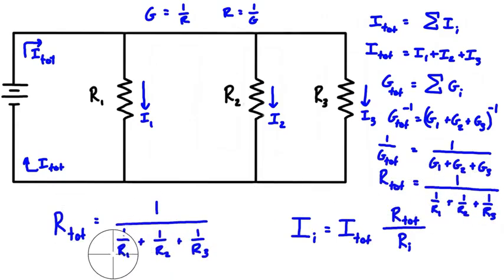So that's exactly how you derive this equation, which gives us the equivalent resistance of the circuit from the perspective of the battery. So instead of having these 3 resistors, we could cut these and remove the right-hand side of the circuit and then just connect one equivalent resistor here. As long as that has this resistance, then the voltage source really could care less if it's one single equivalent resistor or the 3 actual parallel resistors.